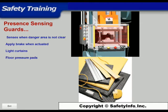Presence sensing devices detect the presence of a person or part of a person in a defined area and prevent the dangerous parts of a machinery from moving when the danger area is not clear. The most common presence sensing device are light curtains. These devices immediately apply a brake or prevent actuation of a machine if the light field is broken by a body part or other object.